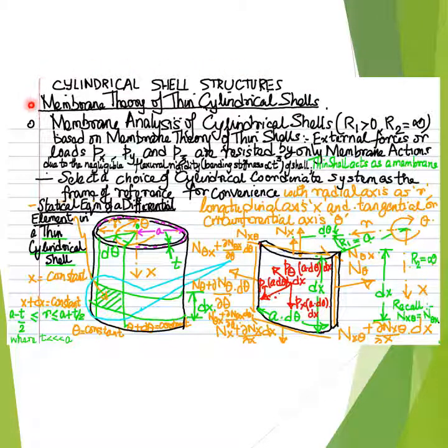And the membrane analysis, that is, the analysis of the shell element for the solution of the unknown internal membrane actions, therefore resulted in the 3 unknown remaining in-plane internal membrane actions, which were Nx, Ny, and one of the two, Nxy or Nyx, after the application of the 3 moment equilibrium equations.